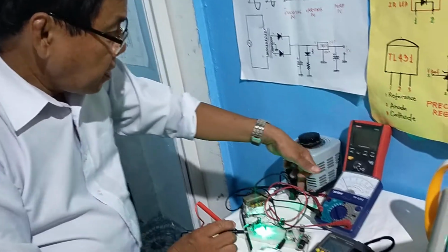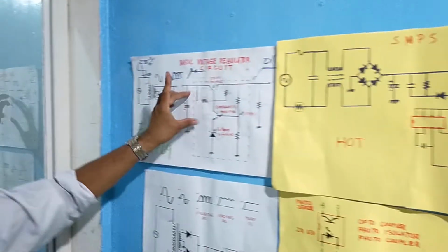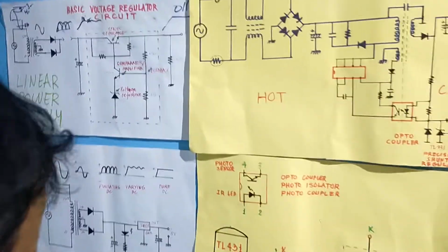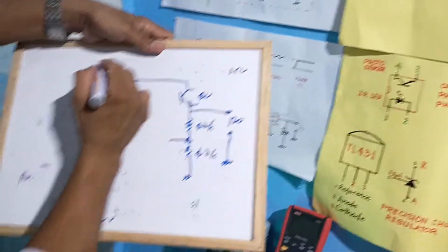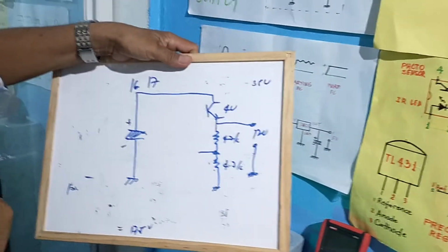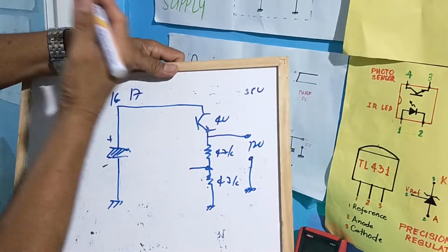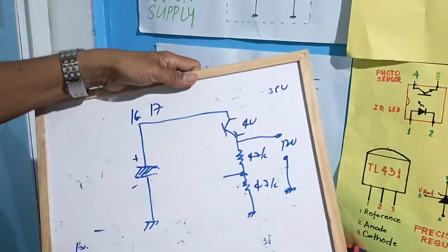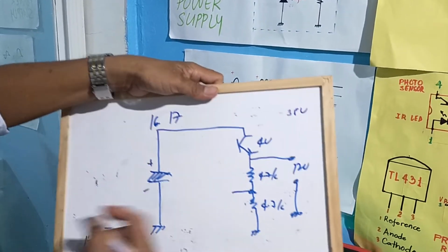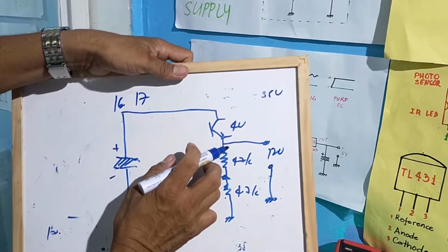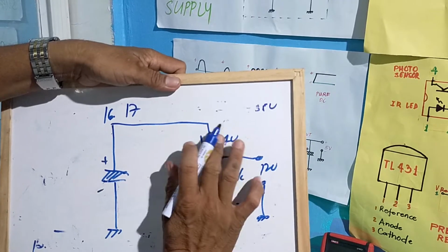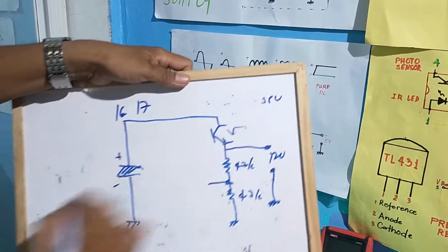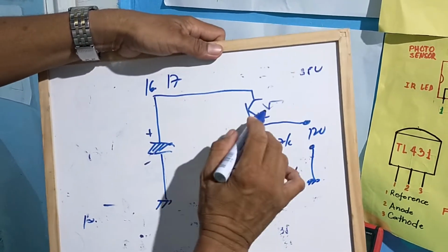Now the voltage at the outlet is increased to 244, and the voltage across the capacitor also increases. So when this increases to 17 volts, because of the increase at the outlet from 230 to 240, the voltage at the output should remain 12 volts. So what is changed now is this one here. This will be changed to 5 volts. 12 plus 5 is 17.